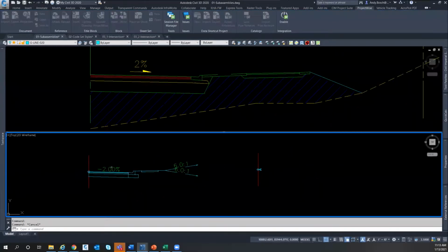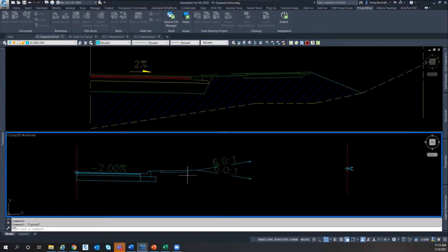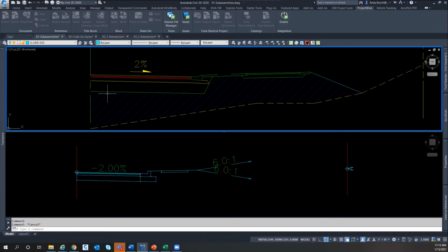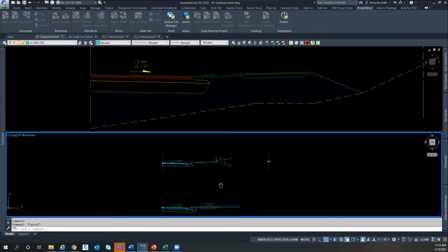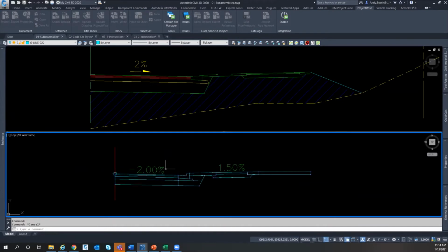So that's out of the box. Probably a little underwhelming if you're going to get into some heavy roadway design. It's not going to get you to the full point of really what you want to see, not only for your cross sections, but what you want to get out for earthwork. So I'm going to cycle down and show you some stuff. This is some more custom subassemblies. And this is what you can start to build in the SubAssembly Composer.